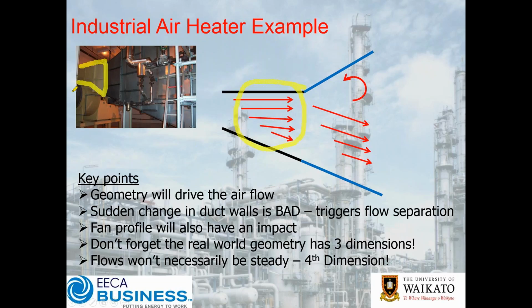Now, obviously, what then happens, if I get those markings out of the way, when we get to the fan transition where we now go into the diffuser, you'll note in this particular installation that the lower edge of the diffuser follows nicely the fan outlet duct, whereas the upper end of the diffuser goes off at a rather sharp, nasty angle.